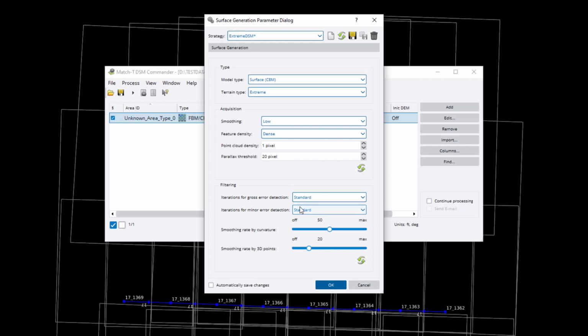And if we filter more out, then of course we have no false data, but we smooth it more and more, and additionally we will lose these peaks and small details on top. So therefore we are now on purpose trying to reduce these values so that we can get more of the top of our objects and trees and whatever we call a DSM.